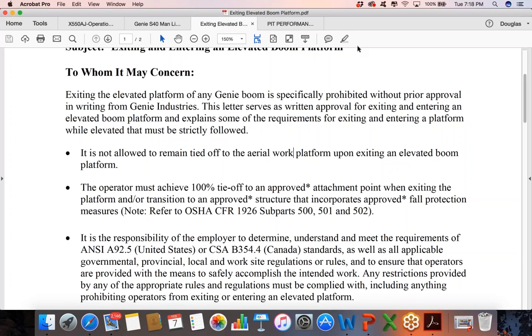Also, let's talk about safeguards a little bit, to prevent injuries or property damage. What are we talking about? Well, steel erection. What kind of work processes do we have going on? We have grinding going on, cutting going on, welding going on. These are all processes that we have going on during the steel erection stage. We want to make sure that we have proper clothing: long sleeve shirts, full length pants with no cuffs because of the hot work hazards that may be going on.